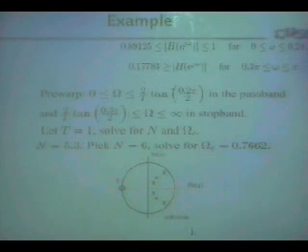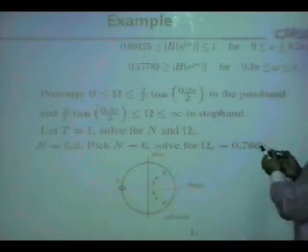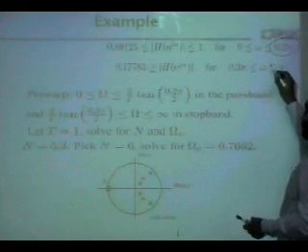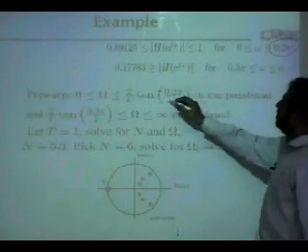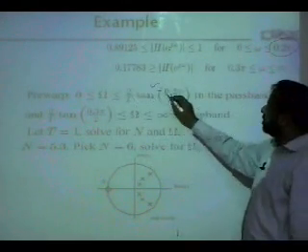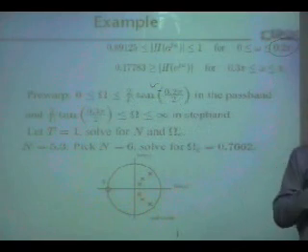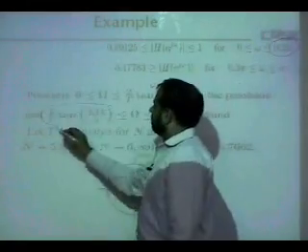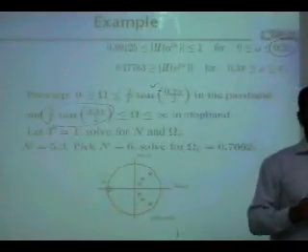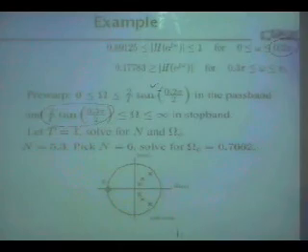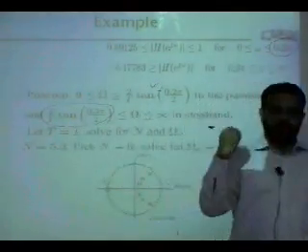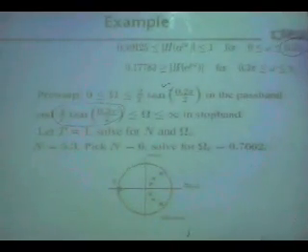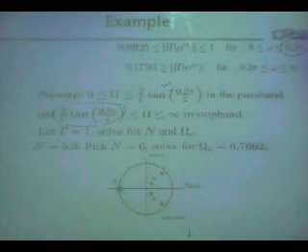So here is the same example, but now first you need to convert this frequency into capital omega. And how do you do this? It is using this formula, 2 over capital T tangent of 0.2 pi over T. So use your calculator, find out a value. So that is this, and similarly you need to do it with this frequency as well. Keep T anything which you want. Here it says capital T is equal to 1, so just take this, but remember you must use the same value of capital T once you are converting HC of S back to H of Z.